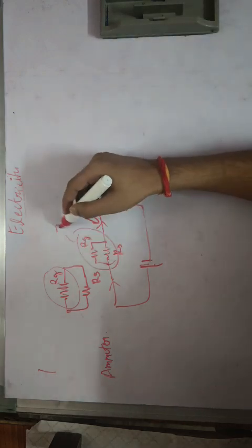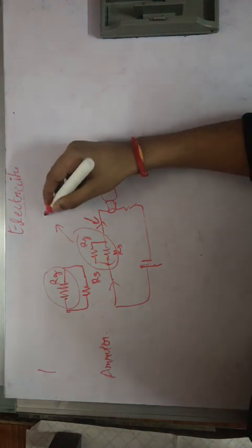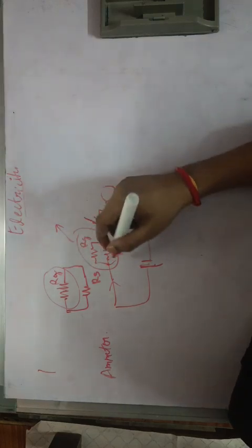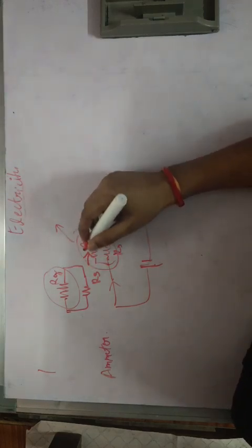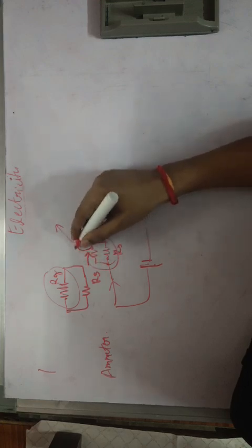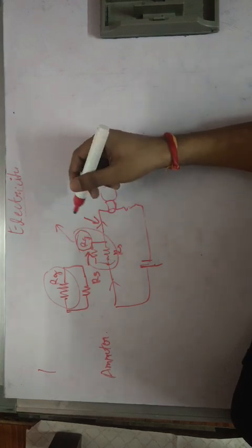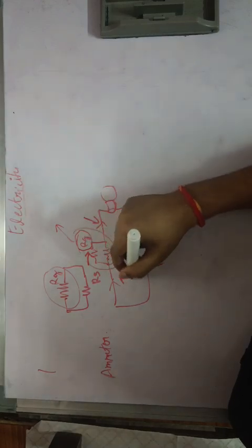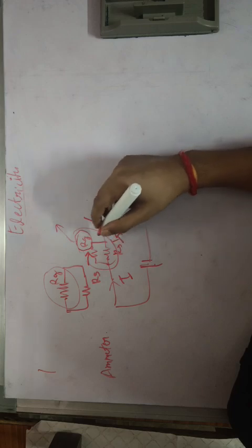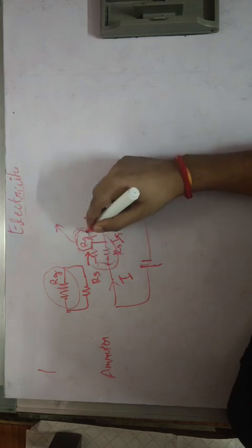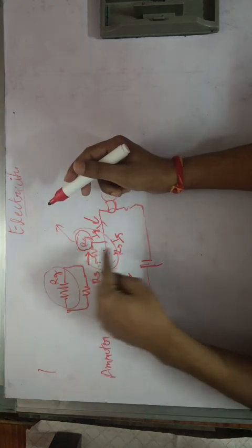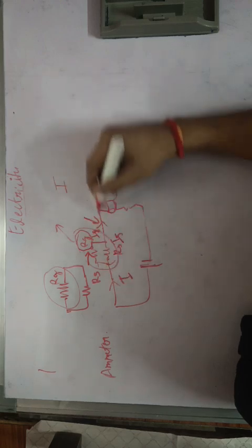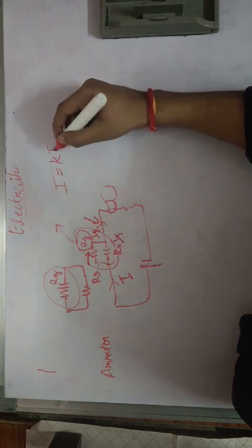This whole ammeter is made in such a way that it measures the current passing through the galvanometer resistance and converts it. Let's say the current flowing through the circuit is I, the current flowing through this shunt is Is, and the current that will flow through this galvanometer is Ig. This is a current divider case. So the total current passing through this circuit is equal to some K times Ig.